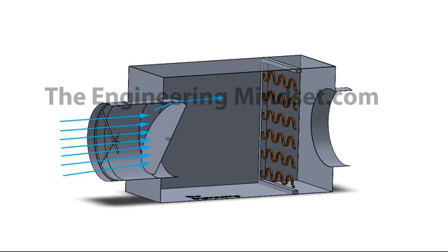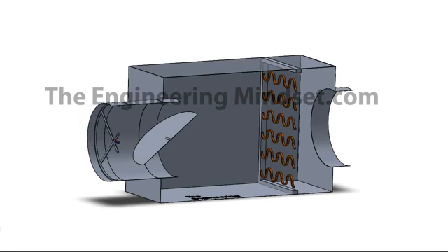But if you've suddenly got a higher heat gain within the room or in the zone, and the temperature in the room starts to rise above the desired set point, then the damper will start to open, and this will allow more air into the space. Remember, the air is about 13 degrees Celsius, 55 degrees Fahrenheit, so that will start to cool the room down and force all that hot air off into the return duct.